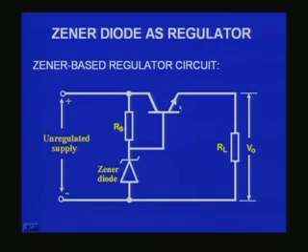That is the basic feature of a transistor. So this current amplification is called beta or HFE, which we will discuss a little later. This multiplication factor between the base current and the emitter or the collector current of a transistor is exploited in this case to design a regulated power supply which will give me a much higher current rating than what I would otherwise get from a normal Zener diode.